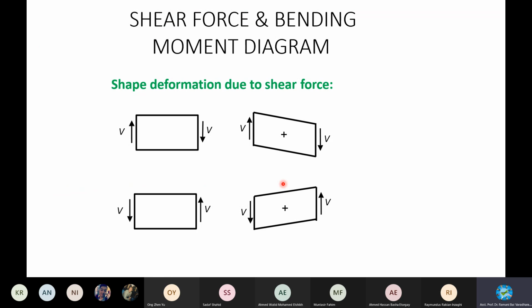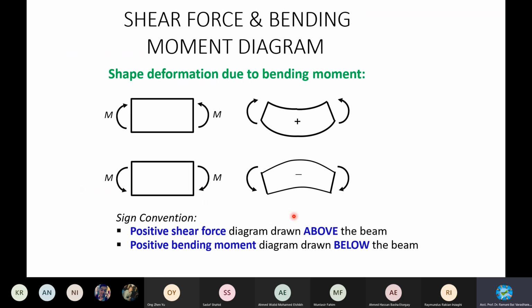That's why we are following one rule: shear force upward is positive, shear force downward is negative, right? In this case, it is taken as a member altogether. When you see the member is lifted, going up, and here also the member is going up, that's why the total is said to be 4. Or in one word, all upward direction forces are positive, and downward are taken as negative. Keep this in mind.